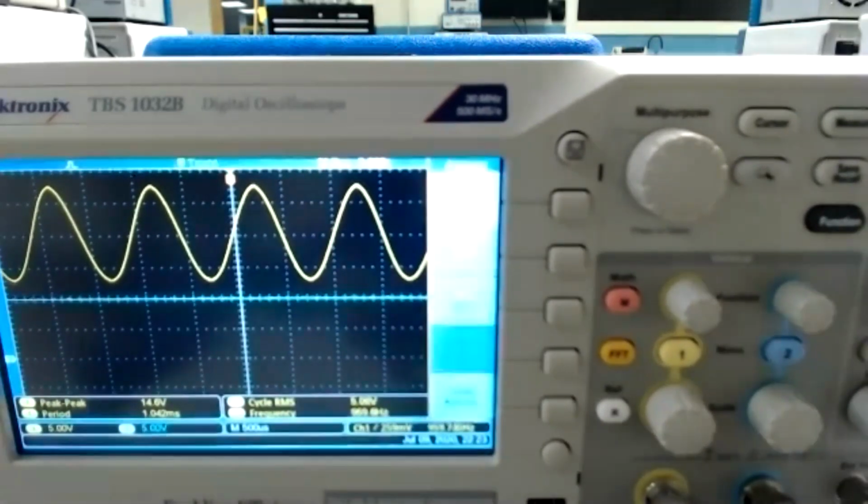I'm gonna repeat them again. For channel number 1 or column 1 of your logbook or a spreadsheet, whatever you're using to take notes, we have voltage peak of 14.6, peak to peak, my bad, voltage peak to peak. We have a period of 1.04 milliseconds.